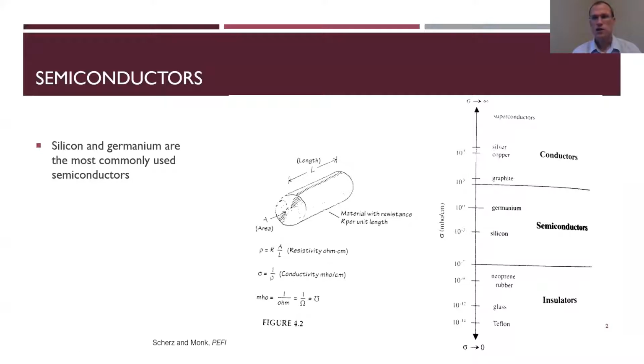So semiconductors are kind of in the middle between conductors and insulators, based on their conductivity, which is 1 over the resistivity. We saw resistivity before. Conductivity is the inverse of that. Conductors have really high values of conductivity. Insulators have really low values, so 10 to the negative 12, negative 9. Semiconductors are kind of around the 1 range, so they're right in the middle. 1 to 10 to the negative 3, so those are our semiconductors, usually made out of silicon or germanium.